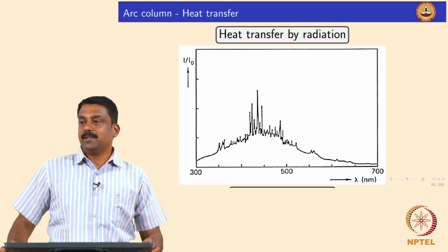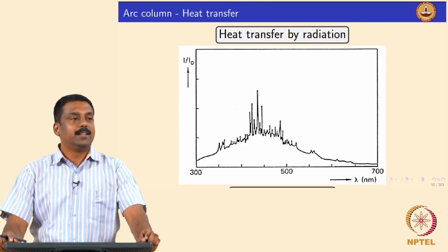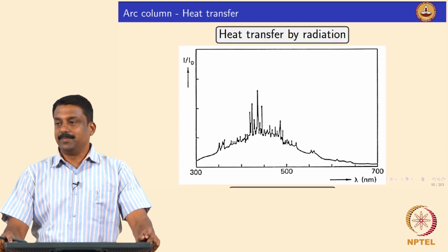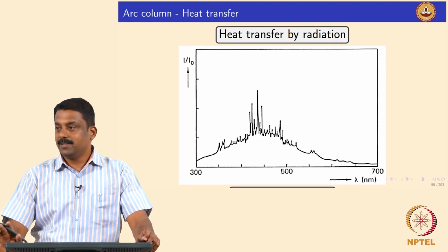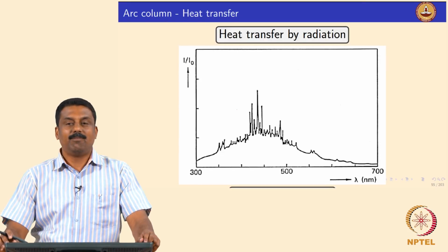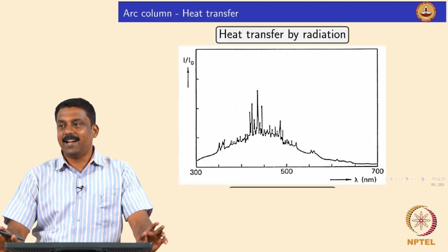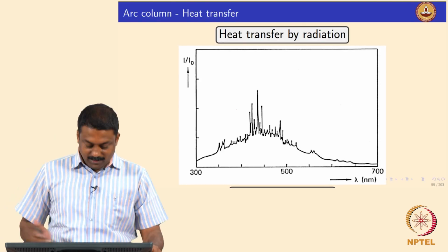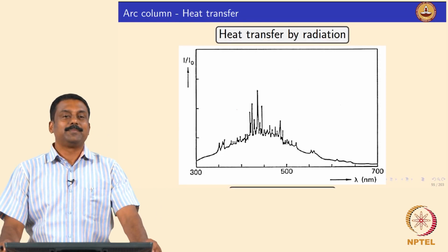So the second heat transfer, which is also very significant in terms of arc: heat transfer by radiation. Have you seen an arc? What is the color of an arc? Don't stare at an arc with the naked eye, isn't it? So look at the spectrum. This is the spectrum of an arc.